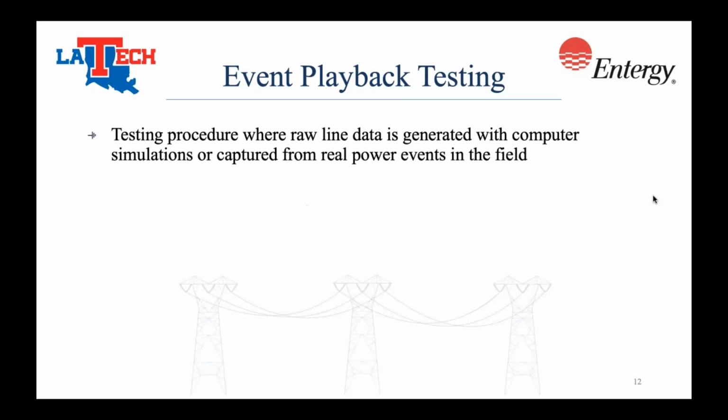New to relay testing is the ability to run playback files directly with only a computer and the relays. This allows high-frequency data simulated in the computer or captured from real-time power events in the field to be loaded directly onto the relays, bypassing the need for a high-bandwidth amplifier. This is a great way to test the relay's response to transient events on the power system.